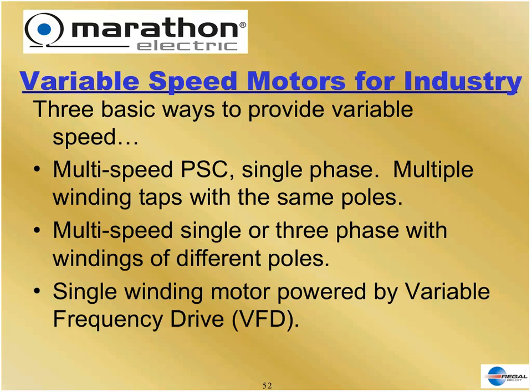So what do we do? Well, in fan loads, we build motors like this. We build multi-speed PSC single-phase motors. We put multiple speed taps in. What the speed taps do is strengthen or weaken the motor that changes the slip. It makes the motor stronger, faster, or weaker, slower. Kind of like a ceiling fan. You pull the chain, you got medium speed. You pull it again, you got low speed. Okay?